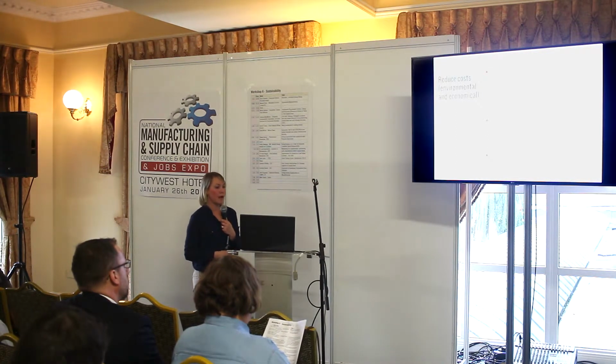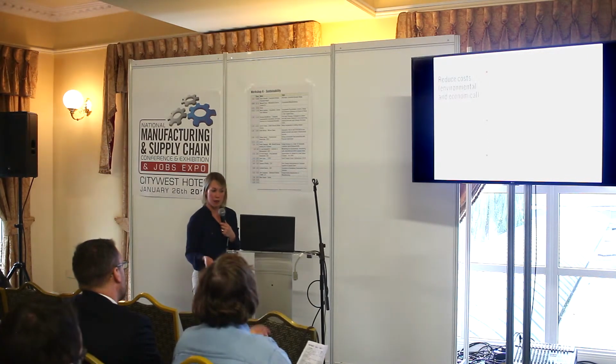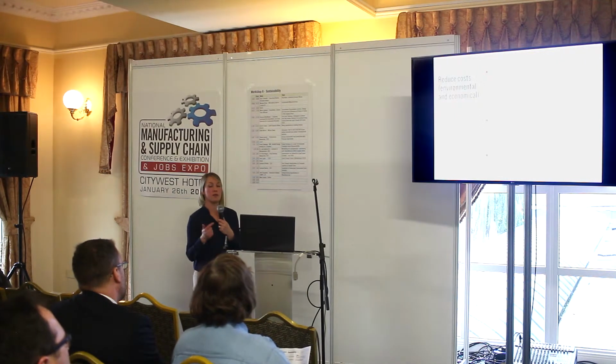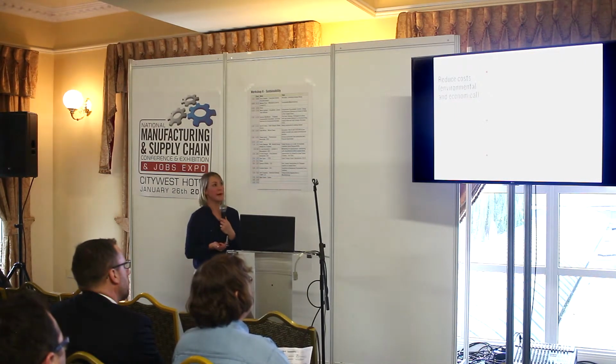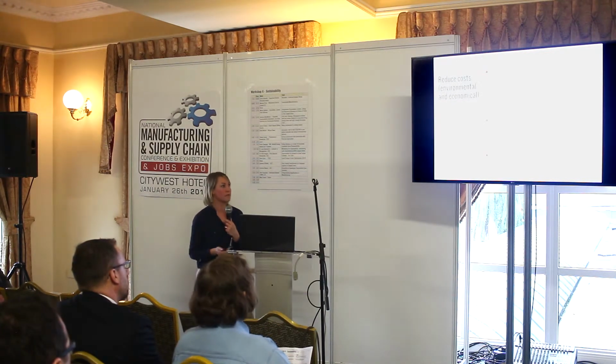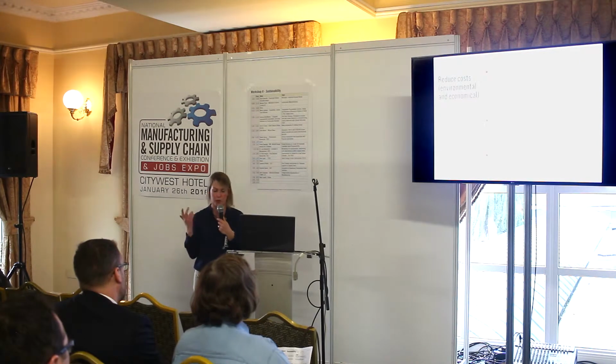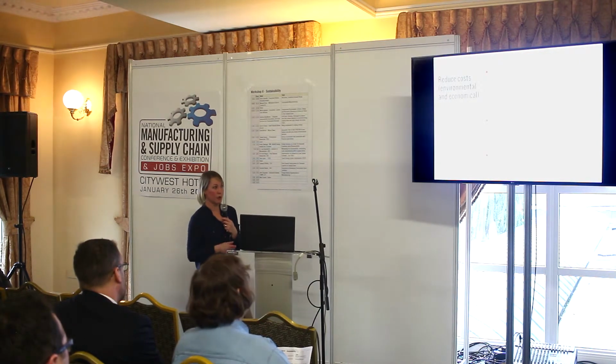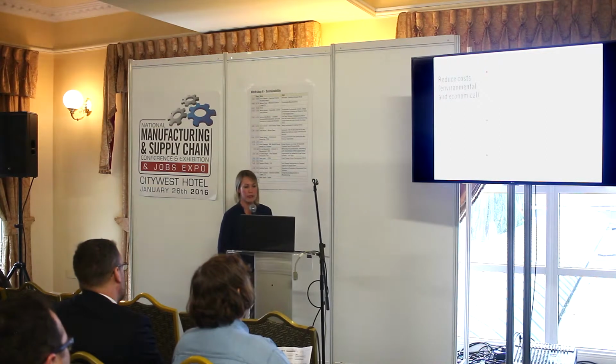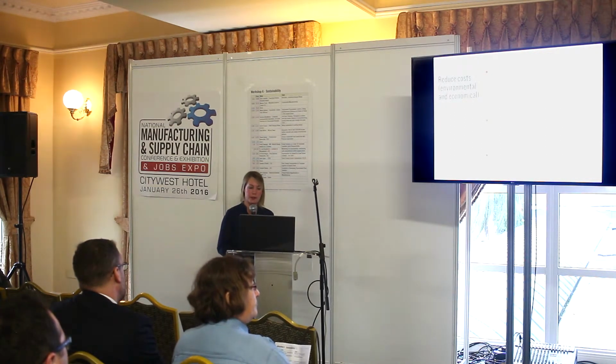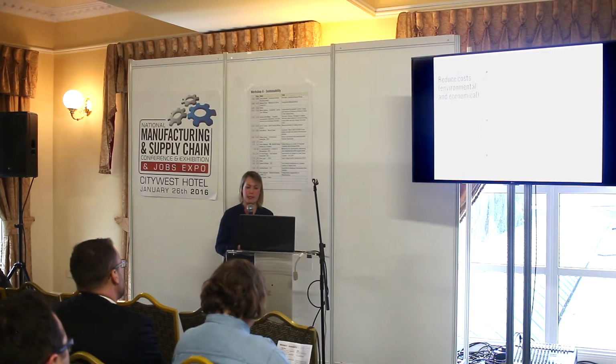What I use is I compare that with a lifecycle cost assessment, where you can quantify using your bill of materials, for example, the cost of all the components, and say, well, if we remove 4 screws from the bottom of this product, it'll have a cost impact of such and such, or at the very least, know where your big cost drivers are and where you should focus your efforts. And essentially, it helps inform your design decisions. So before you go to your product development team, or before you go to your colleagues, you have a lot of data to back you up, and you have an understanding of where they're coming from, essentially.